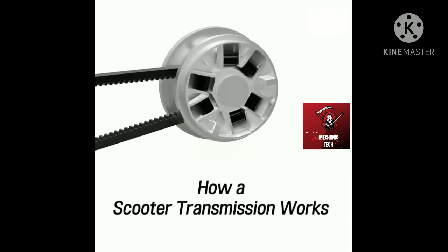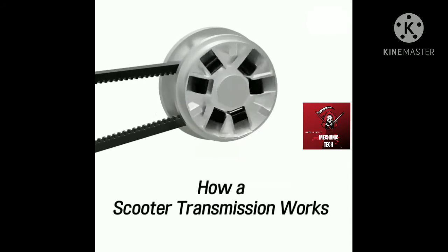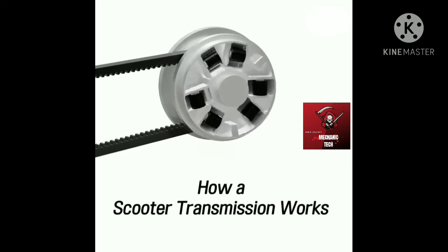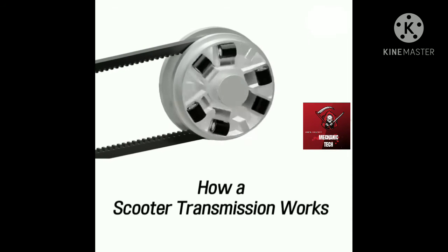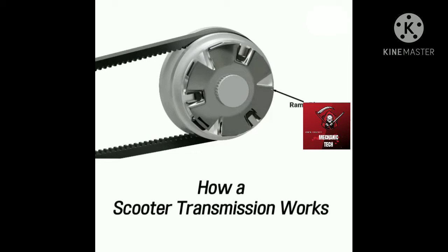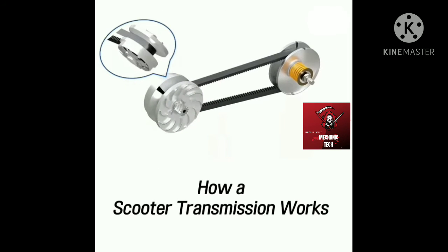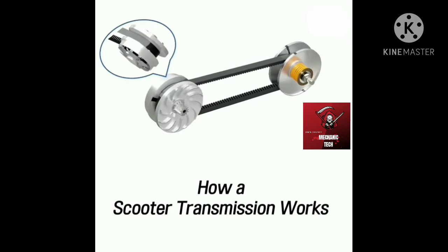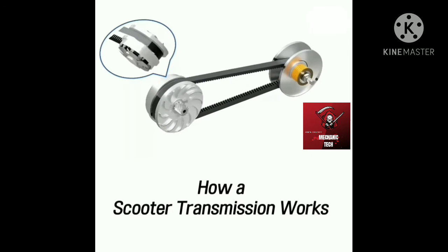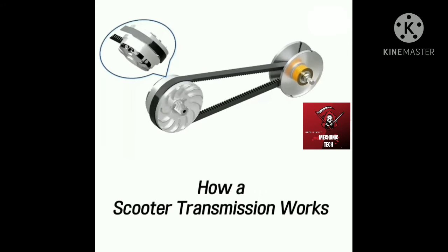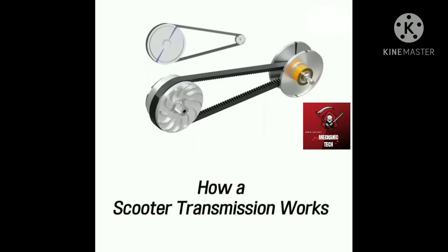As the engine gains speed, centrifugal force causes rollers to move outwards along a curved surface. These rollers push against the ramp plate. Since the ramp plate is fixed, the sliding conical plate is forced towards the other plate. Let's see the diameter change in slow motion. This is similar to the condition of high RPM, low torque, as we observed in the demonstration.